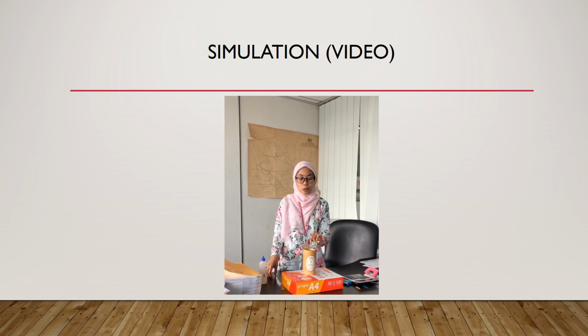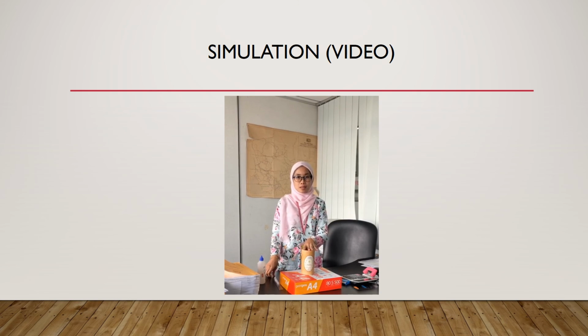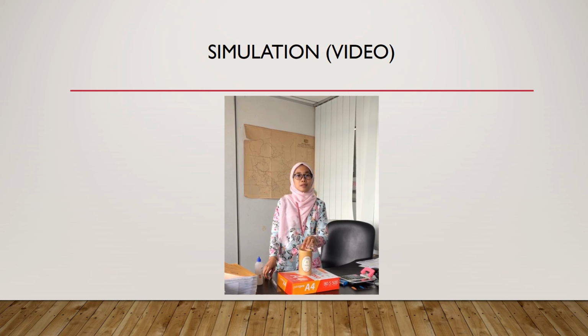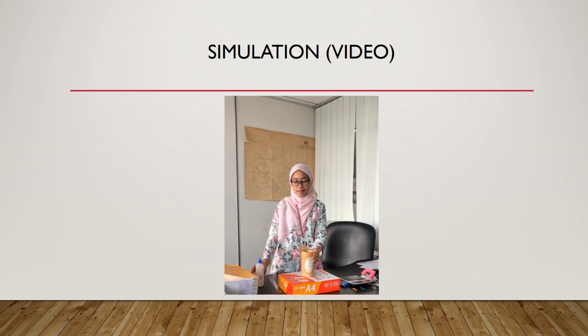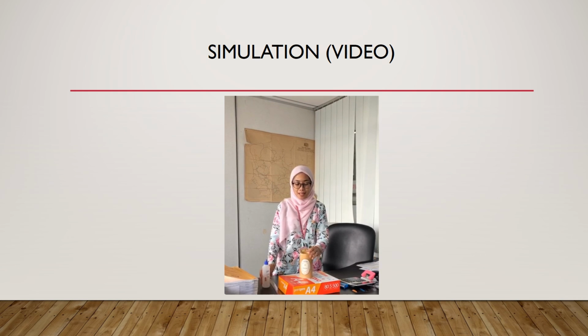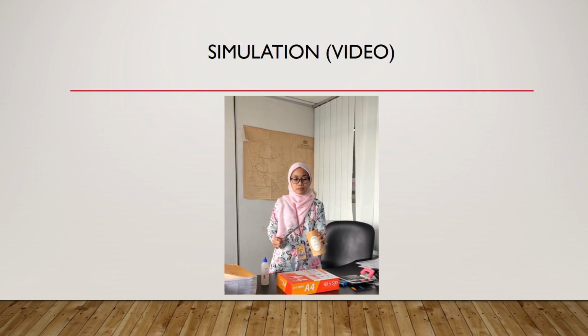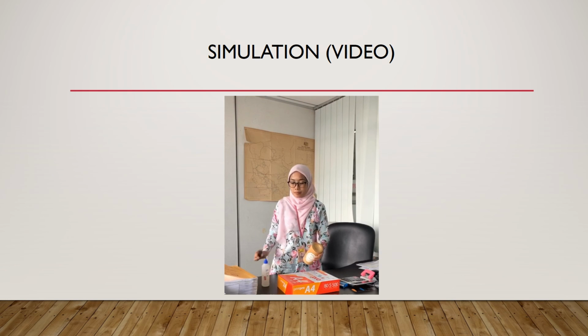The objective of the point load test is to determine the strength of rock material through an index test. This is the material and this is the machine. Firstly, measure the diameter of the sample and the length of the sample.